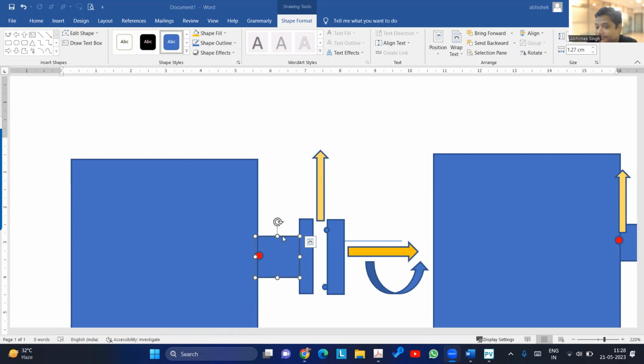Okay, sir. But the problem is that I've seen this with the stresses in the nozzle neck, the nozzle loads consideration, the support design and foundation loads. In one job, there is an EPC and then there is a PMC. The EPC is saying that don't consider nozzle load because it is enhancing the foundation loads, and our foundation is becoming bulky, and we have to bear that cost.